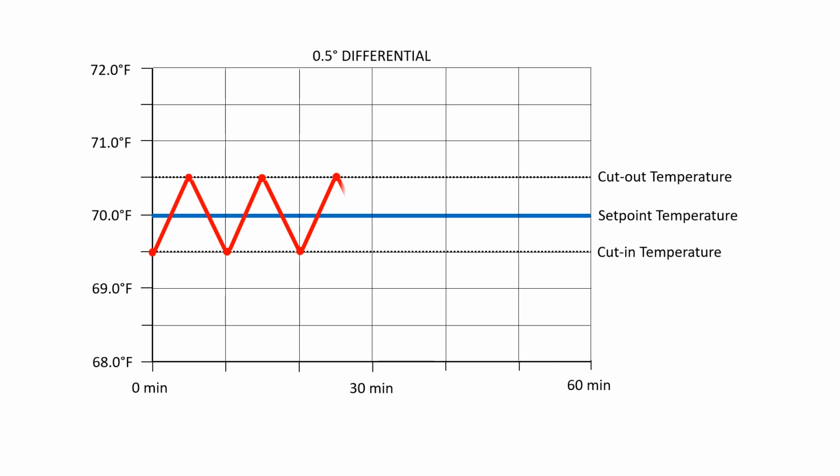When a heat pump compressor first starts, it is not efficient. It takes a few minutes to become efficient, and with a fast cycle rate, you can see the unit will turn off before the compressor reaches peak efficiency. This thermostat turns on the compressor and allows it to operate for about 5 minutes, and then turns it off. The compressor did not run long in peak efficiency range.